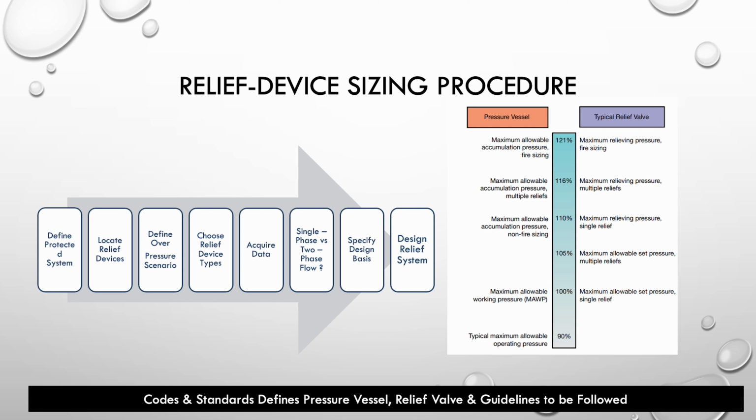You have a given loop around the heat exchanger, for example, and you're gonna need to be picking the weakest link in that loop. Most likely, it's going to be a process equipment, not the piping. Piping is probably the least of your concern, because given how cheap, relatively speaking, the piping is, you're most likely protecting a piece of equipment, whether it's a heat exchanger or a distillation column or a reactor. That's why most of the time you're gonna find the relief valves are always on a piece of equipment, not on a piping. Right.